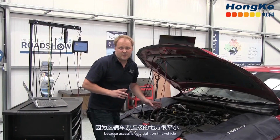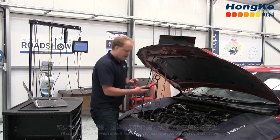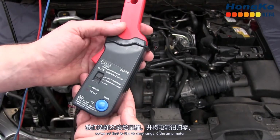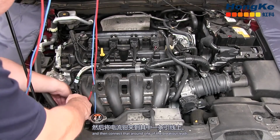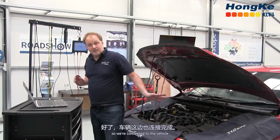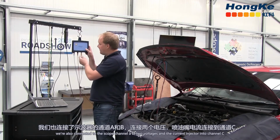Because access is very tight on this vehicle, I've used breakout leads, which make it much easier to get the probes onto the right connectors. So we've done the voltage, now we're also going to use a current clamp to look at injector current. We've set that to the 20 amp range. We zero the amp meter, and then we connect that around one of the breakout leads. So we're connected to the vehicle. We're also connected to the scope, channel A, B, two voltages, and the current into channel C.